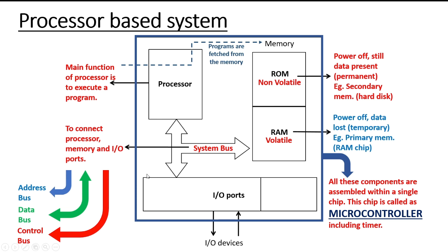Hardware delay is produced by a hardware component which is physically interfaced with the microprocessor, and the software delay is nothing but instructions or programs in iterations used for creating a delay. So when you use the hardware delay, there is a separate component which counts for the microprocessor.